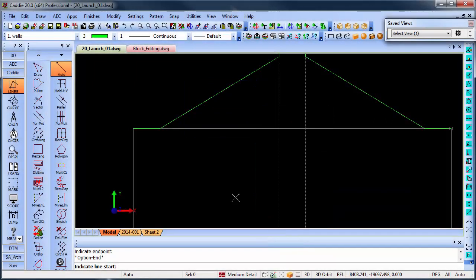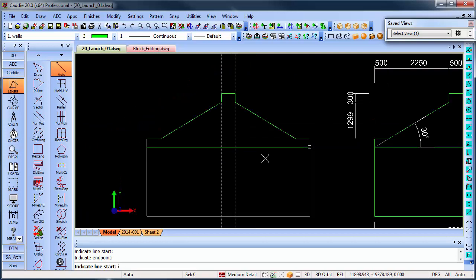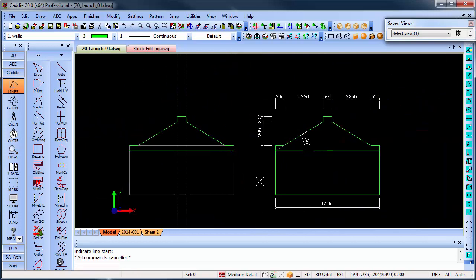Now all I do over there is I hover my mouse over that line, and you will see it projects that line down automatically. So once again, use that in conjunction with your polar tracking, meaning the line starts there, projects horizontally over there, and there you've got exactly the same as we've had before on the sample side of the drawing.